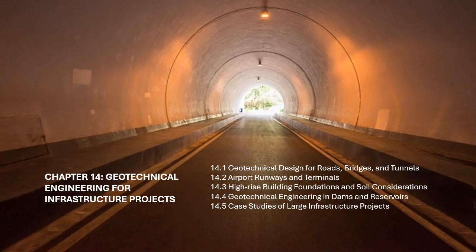Geological and geotechnical surveys. A comprehensive geological and geotechnical survey is essential for identifying subsurface conditions and determining the type of tunnel support system required. For tunnels in rock, engineers must assess rock mass properties, including strength, jointing, and permeability, to select appropriate tunnel boring machines, TBMs, or drilling methods.